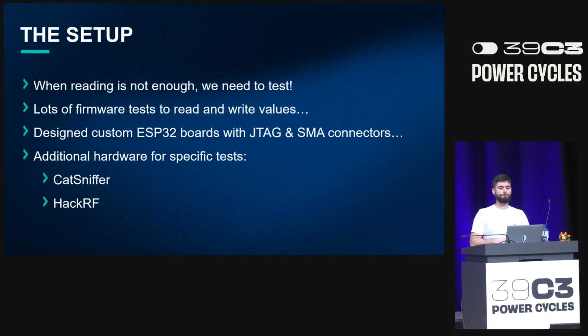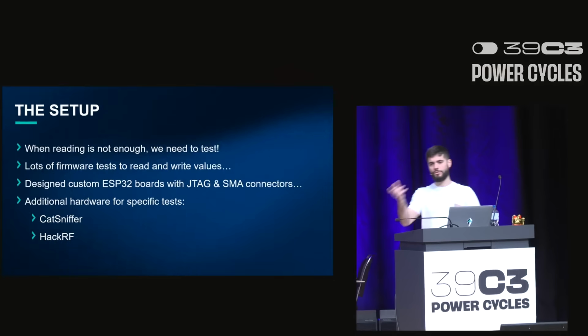So we also built a lot of small firmware tests that read and write values to those memory regions. And we even designed some ESP32 boards that had a JTAG for us to be able to debug what was happening, and some SMA connectors to be able to connect our ESP devices to some specialized hardware, mostly a Cat Sniffer from Electronic Cats and a HackRF from Great Scott.